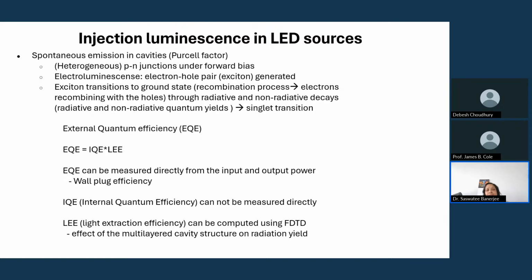This is the case for LEDs, because what we are really doing is making PN junctions. So what are PN junctions? You have two semiconductors, one P-doped, one N-doped. And then there is one little thing about it: the lattice constants have to match, okay?